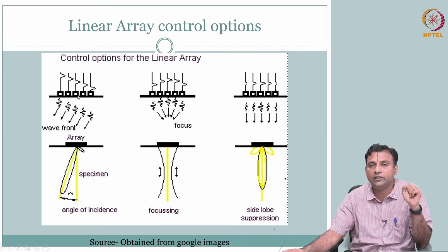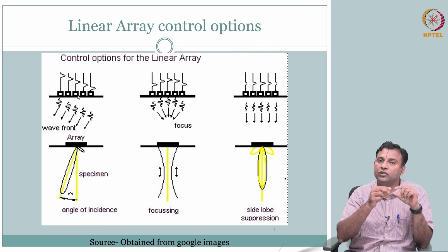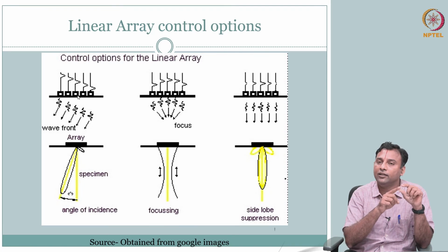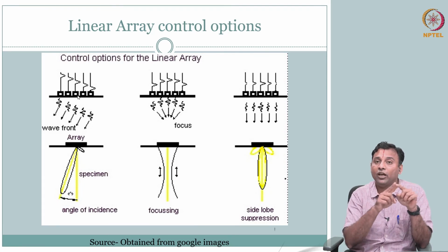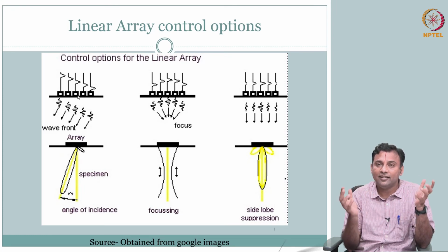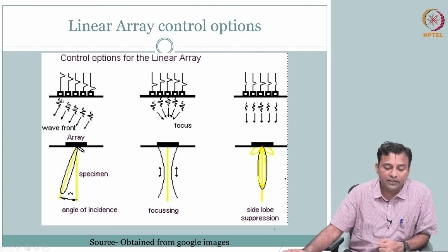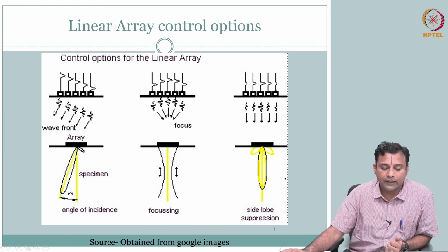So now you see the challenge. If you have a smaller crystal, you have to have electrodes that are also correspondingly small. Not only that, there shouldn't be crosstalk, right? So you have many of these, then the complexity goes up. But the advantage is you have all these crystals next to each other, each one can be excited. You can independently send electrical voltage here, and whatever hits this crystal alone, you will be able to receive the corresponding voltage and play with it, right? Corresponding signal you can get.